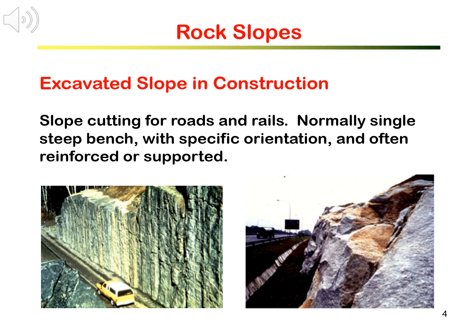Because of the directional characteristics of roads and railways, for example, running north-south, slopes also have specific orientations. For example, again, facing east or west. We will learn later, given the same rock mass, the excavated slopes on the two sides will sometimes have very different degrees of stability and require different degrees of support.